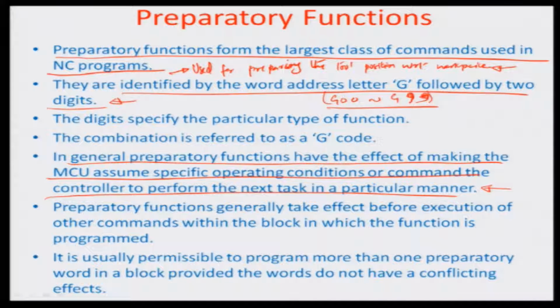So, they are basically one of the first set of commands which need to be there in a block for the block to get initiated or started in terms of its execution. Just following the identification number N, there has to be the preparatory function enabling the system of motion, which is governed by all these stepper motors etc. within the machine, to start getting prepared to do its job of the relative motion. Okay. So, that is why the name preparatory.